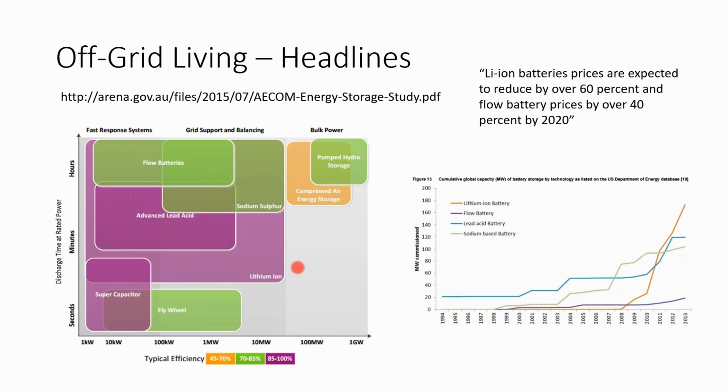In an off-grid system, you want to make sure that your batteries are topped off every single day. And so if I'm living off grid, I'm going to be oversizing my solar array regardless of what kind of battery technology I use. And so the efficiency of my system is not that important.